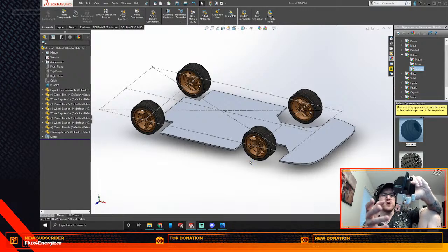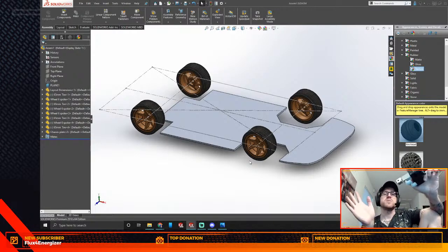So a couple of things that you can do to mitigate that. You can make your heat break out of titanium to help prevent that heat from creeping up. And you can also increase the cooling of your cool zone. So water, absolutely amazing at cooling.